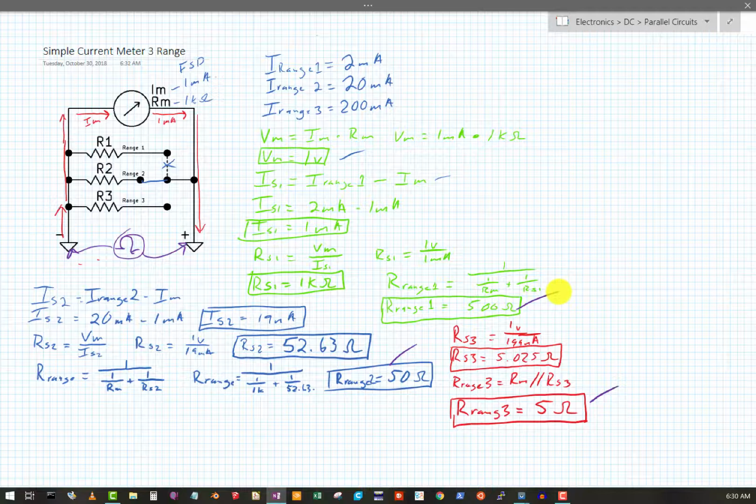These are very small resistances, so to measure current directly, you're definitely going to run into some current meter loading problems with your DMM, and I'm going to hopefully get another video soon of the measurement process. Because the resistances are so low, current meter measurements are kind of impractical unless you know the range resistance for your DMM and can account for that.